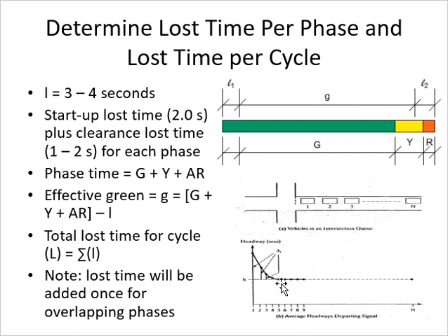Okay, so the normal headway starts to be observed after the fourth vehicle from the queue. You observe the first 3 or 4 vehicles, they will give you a certain value of headway each, and then you observe the other vehicles of the queue, the ones who came after the fourth vehicle.